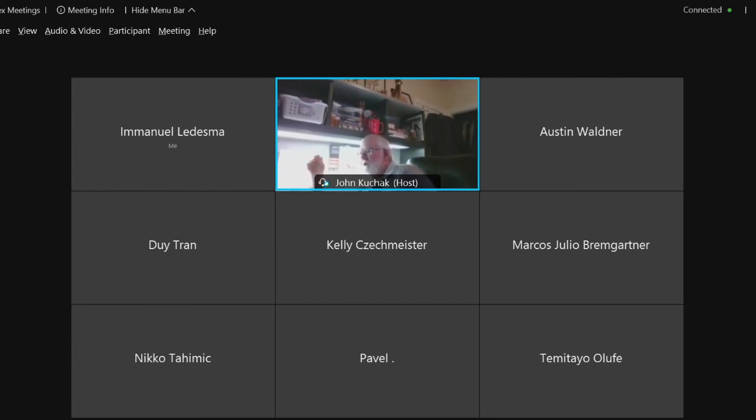All I know is that you're taking 65% of the initial grading of the coarse, and then you're taking 35% of the initial grading of the fine, and you get it combined. If your numbers are correct, then you obviously know what you're doing. Yeah, no point reinventing the wheel. Now, if you copy it off somebody, that'll show up in your exam or your quiz. If you copied and didn't do the calculations, I'll know by you failing the quiz. Okay. And do you have any other questions?